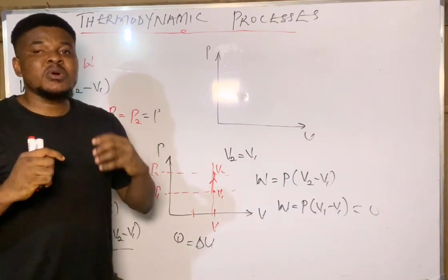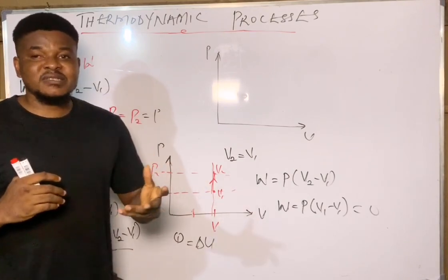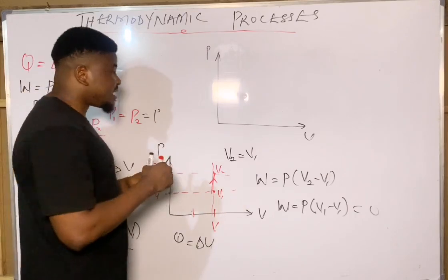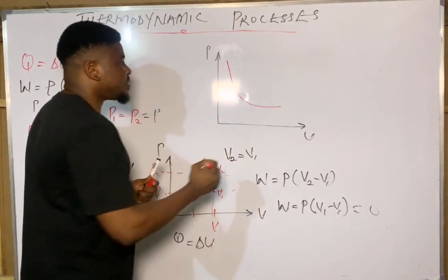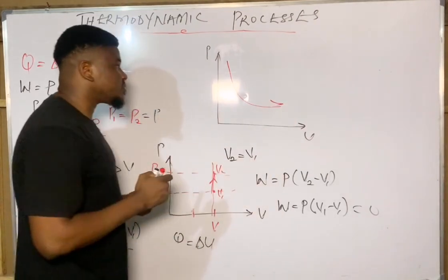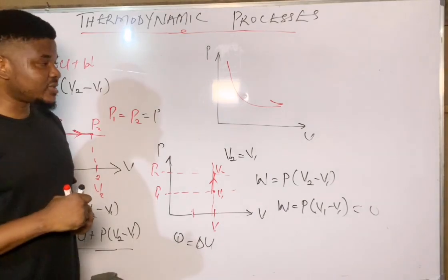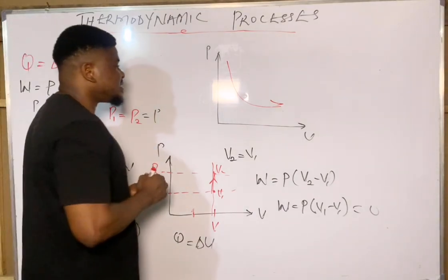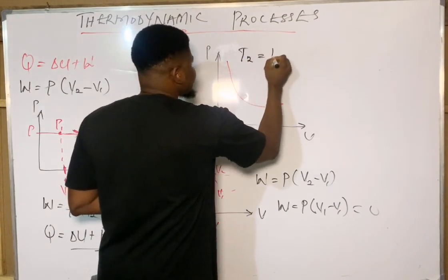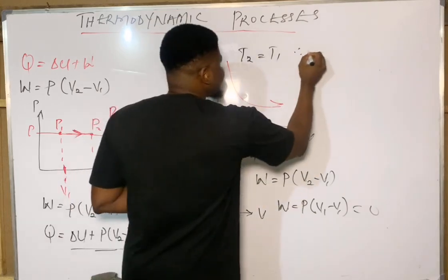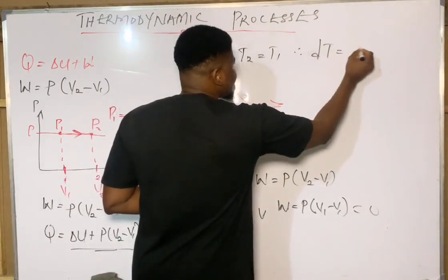The gas cooker becomes an external body supplying heat to the system. So the flow diagram is going to look something like this, because an external body is supplying heat to the system. This is called a constant temperature process. For this process, the initial temperature T2 is equal to the final temperature, and therefore the change in temperature dT is going to be what?